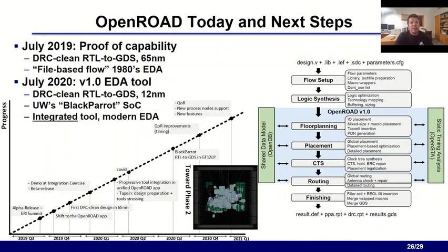And so this is where we are today. The integrated app OpenROAD is in blue and is tightly tied into the timer and the DB. Most of our tools are integrated today and are sitting in a mono repo. This trend of consolidating repos and not using submodules is accelerating in our project. There are 3 other executables in the flow: YOSYS for synthesis, TritonRoute for detail routing, and KLayout for layout finishing and GDS merge.